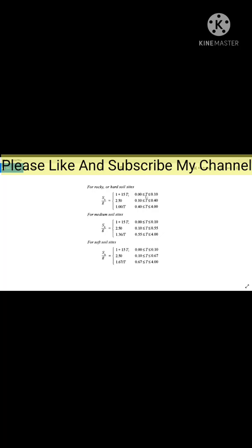So how can we calculate this time period? Soil type we come to know when we calculate the bearing capacity on site; we will get these values on site. But we must know what the time period is. So the time period we can calculate based upon two factors. Okay, whether it is a concrete frame or a steel frame. Okay, so that we can calculate again from the same IS code. I will show you that formula as well.